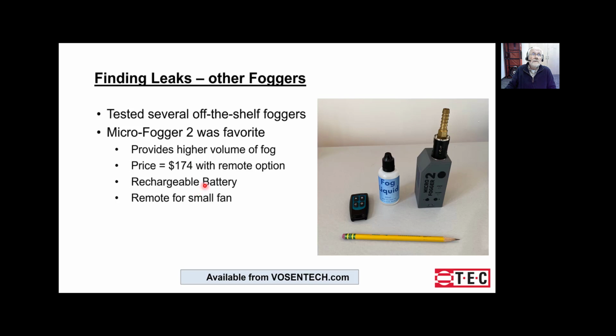Of course, it's a rechargeable battery, and there's a small fan instead of a squeeze bulb to get the air to flow through the device and make the smoke. But I like this a lot, and at least one customer of ours has told me that he's been using this, and he actually says it makes enough smoke to do a leakage test on a duct system by pressurizing the duct system with smoke.